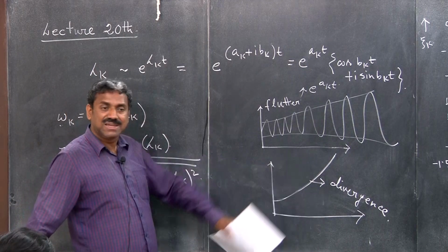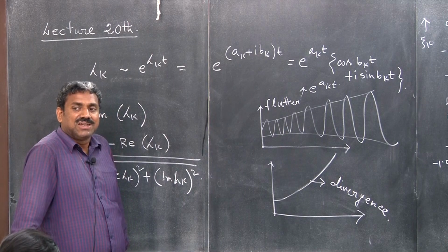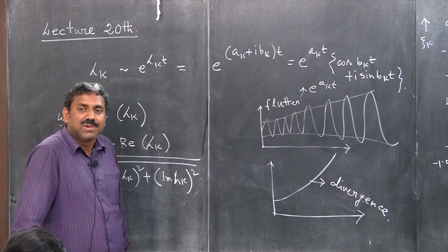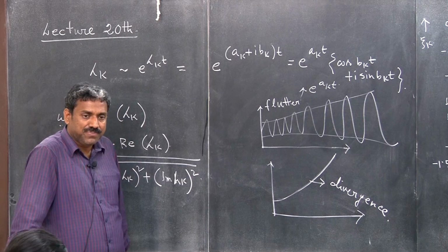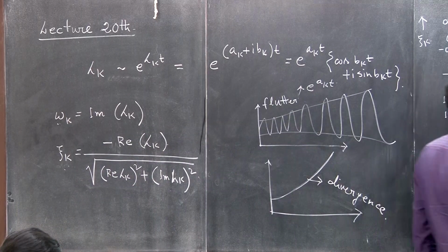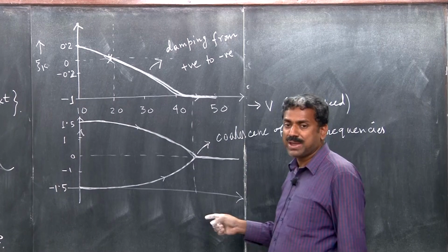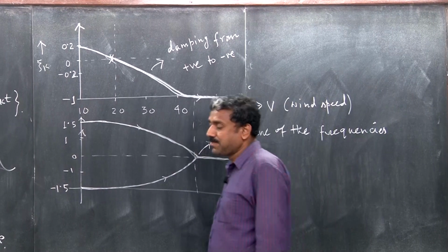So, divergence is basically equivalent to buckling, because essentially its stiffness is all eroded by the geometric stiffness, okay? Because geometric stiffness is being subtracted, and that is what is happening. You see that these two modes are coalescing, and this is becoming 0 frequencies, okay? Now, this is happening for this case.